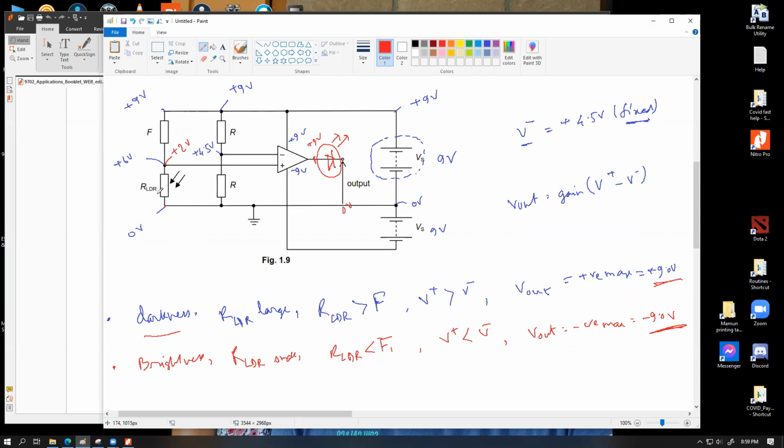In this place, you can place a piezoelectric transducer, which is going to produce its own voltage. So that will give us a pressure detector. So you can input any component in the place of the LDR which is capable of detecting a physical variation, which will lead this same circuit to give us two opposite outputs from the supply.